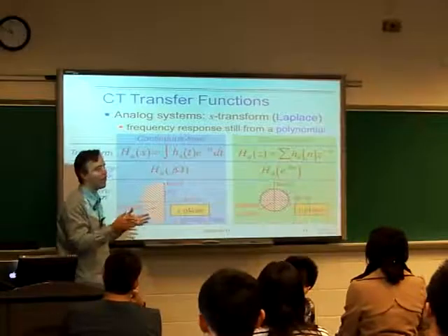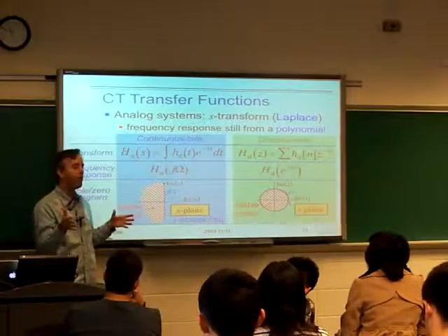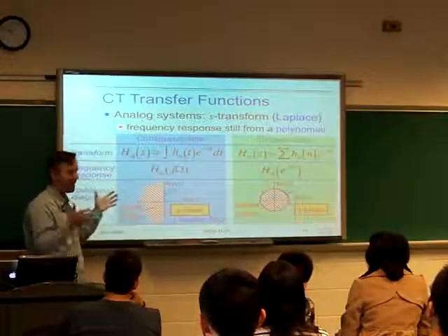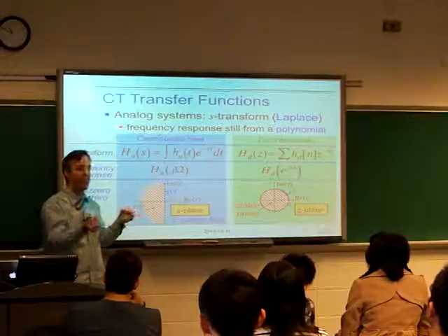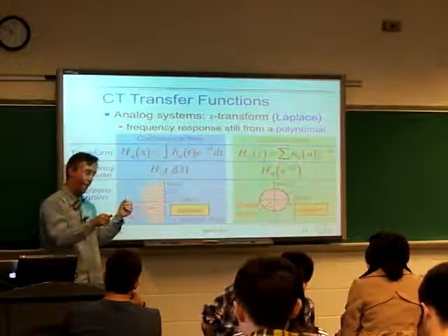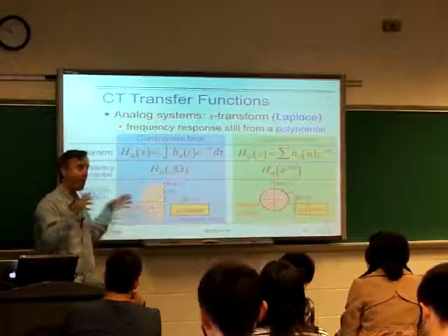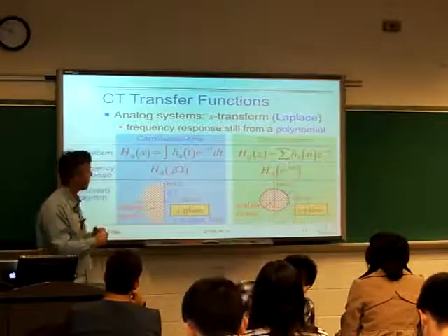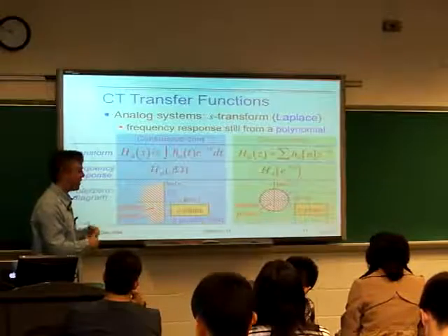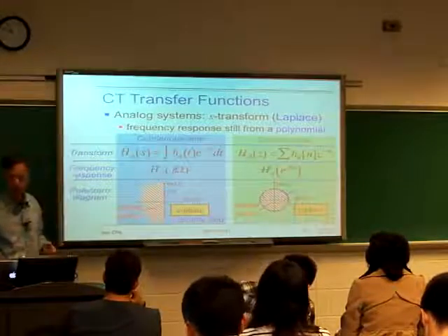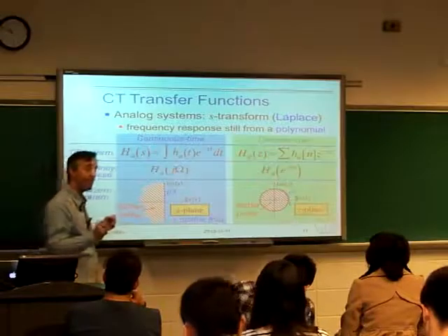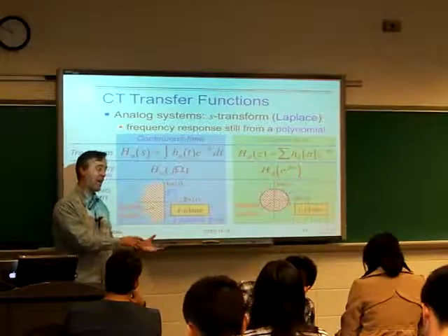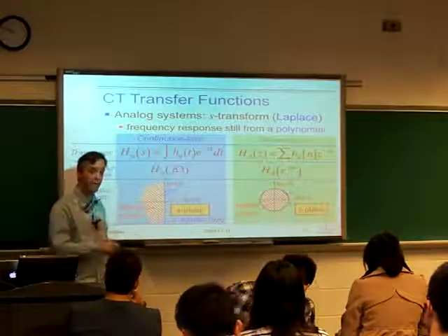And so that means that the idea of trying to change the breakpoint of a filter in the Laplace domain is trivial. You basically have to take your factor and apply it to the coefficients depending on what order of s they corresponded to. You might have to raise it to some power, but it's just a very simple scaling operation to design a filter at 10 times the frequency or something. So we'll see that comes up in these analog filter design processes. What that means is basically when we try and design an analog filter, we design it to an idealized frequency, a frequency of 1, because then once we've got that thing, we can trivially scale it up to some other frequency that we care about.